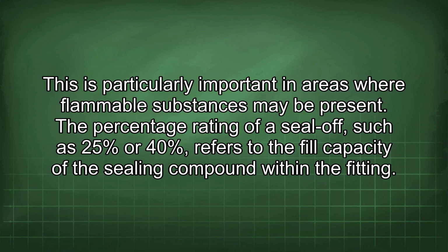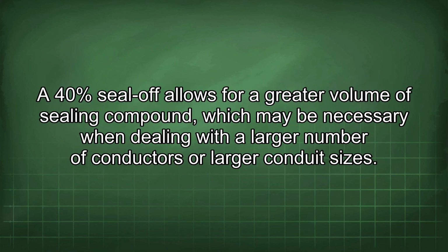The percentage rating of a seal-off, such as 25% or 40%, refers to the full capacity of the sealing compound within the fitting. A 40% seal-off allows for a greater volume of sealing compound, which may be necessary when dealing with a larger number of conductors or larger conduit sizes.